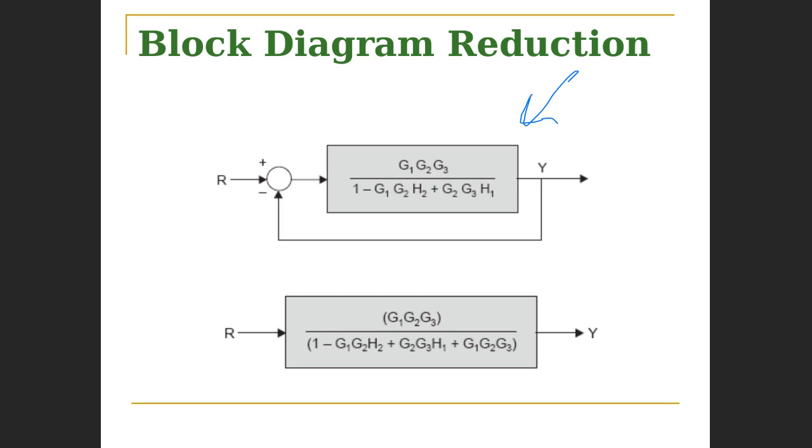Now, you might say to yourself, okay, this looks like a feedback loop. But what about the transfer function for the feedback? I'm not seeing the transfer function. How do we proceed? Simple. There's a feedback loop, but it's called unity gain feedback. So when there is no block in the feedback loop, it's simply called unity gain, for the very obvious reason, right? The gain is 1, so I've just put a box in there with 1 in it.